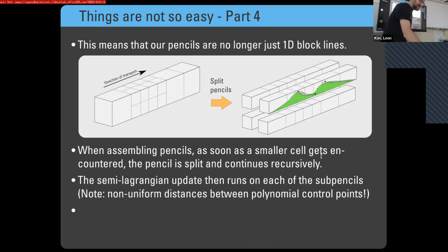And this is very nice because it is really very little diffusive, because we are not essentially losing any information there. We have the volume averages of the cells before, we turn that into control points of a polynomial, which preserves it. We turn that into polynomial components, which is also preserving all the information. And then we put the updated values back.